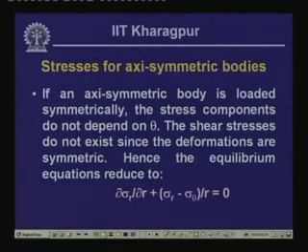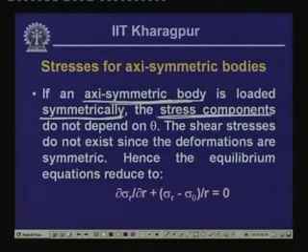So, the bodies which are perfectly symmetrical with reference to their vertical axis, we call axisymmetric bodies. And for an axisymmetric body, if they are loaded symmetrically, this is important, then the stress components do not depend on theta. The stress components do not depend on theta, and thereby at any longitudinal section we take, the shear stress components are absent, because we have symmetric deformation, and thereby the shear stress components do not exist.